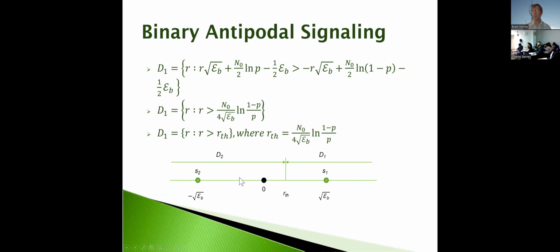So energy is showing how far it is from zero, which impacts how far it is from the threshold. So energy is determining this separation. The variance of noise, or the noise power, is determining how broad that Gaussian distribution is. And what we're concerned with is the distribution here whose tail leaks out over here, right?